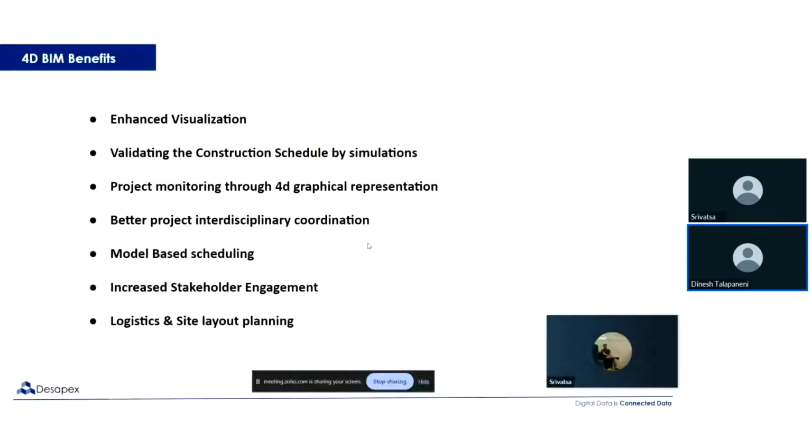So there are certain tools now, Synchro, Excel, and other things where it is capable of developing schedules as well. So you have the model in place and you can develop the schedule directly in those platforms. If not, you can still bring in your MS Project or Primavera P6 schedules into these platforms to run the virtual construction. And by doing all this, we are bringing in the stakeholder engagement, and actually the contractor understands, okay,